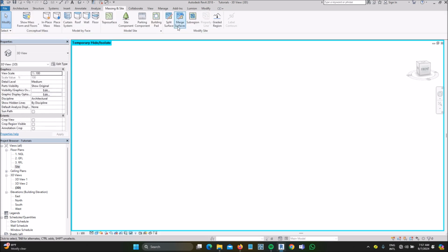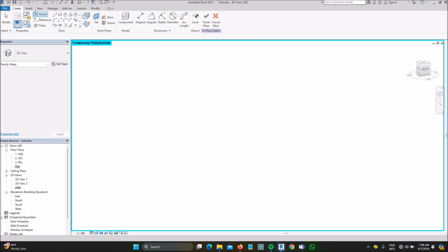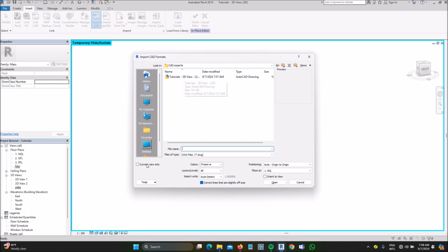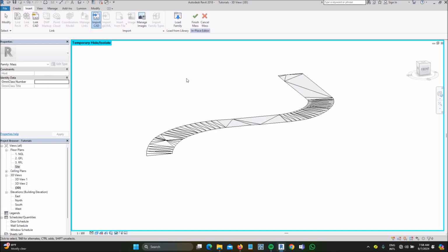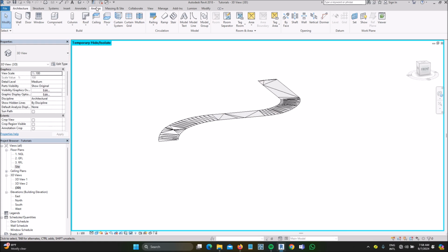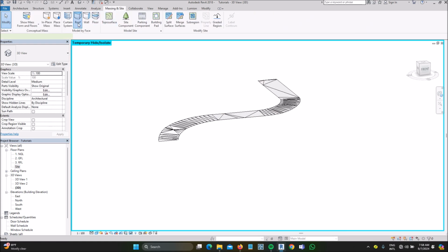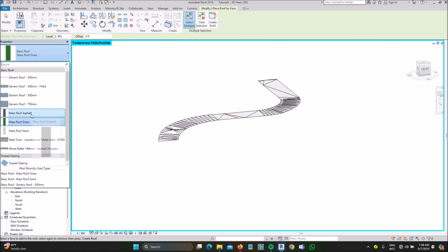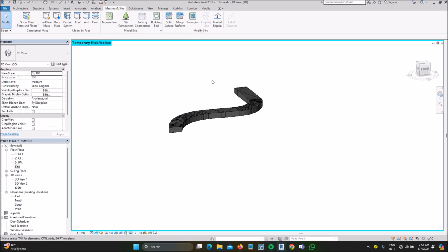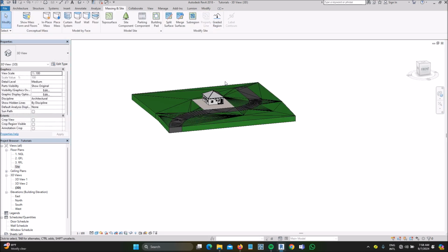Select this, temporary hide it, in place mass, mass 2, start import. So like I said, leave this, import it, finish mass. So the same thing, you go to massing and site, roof. Now mass roof asphalt, press control down, highlight everything, create mass. Okay, so you reveal everything.